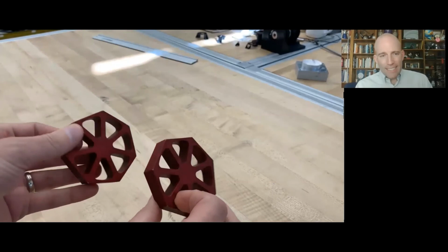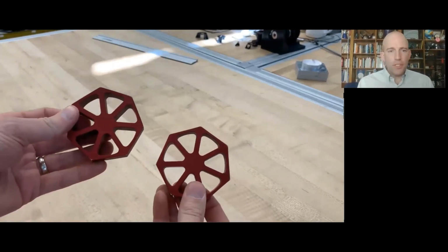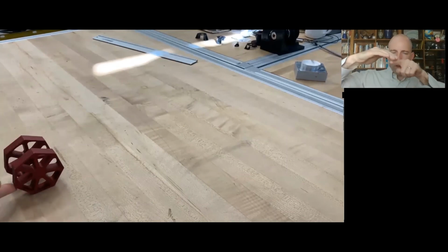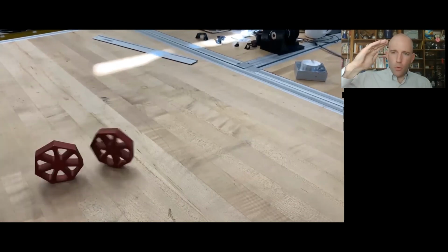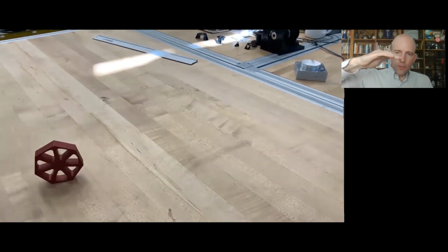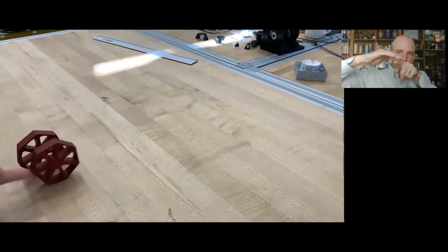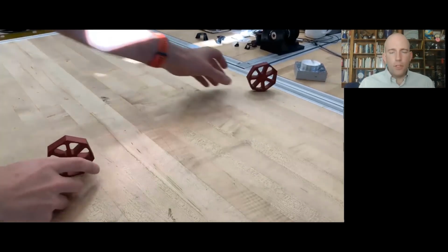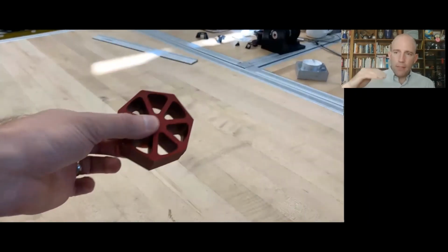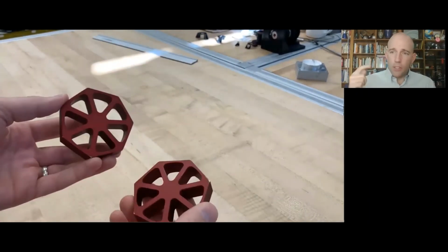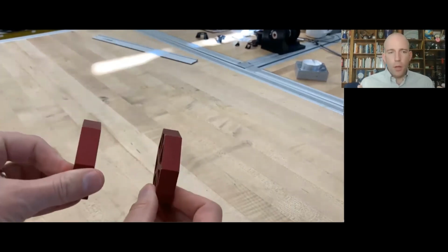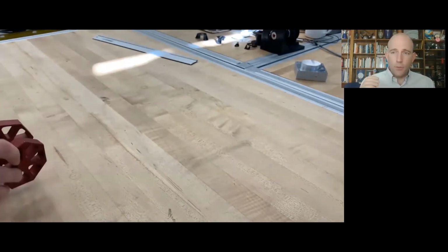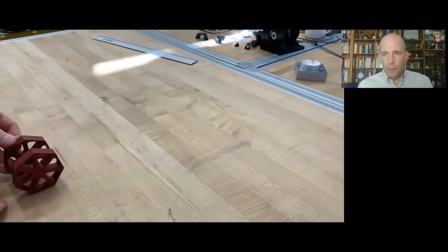With the concave surfaces, the surface goes slightly inwards between the two corners. So when the next corner is about to hit, there's no continuous movement of the center of pressure forward. Instead, bang, instantaneously the direction of the velocity of the center of mass of this Decepticon has to change. There's a collision. It's almost a perfectly plastic collision. A bunch of energy is dissipated, and it only takes one or two of those collisions to totally stop the Decepticon.